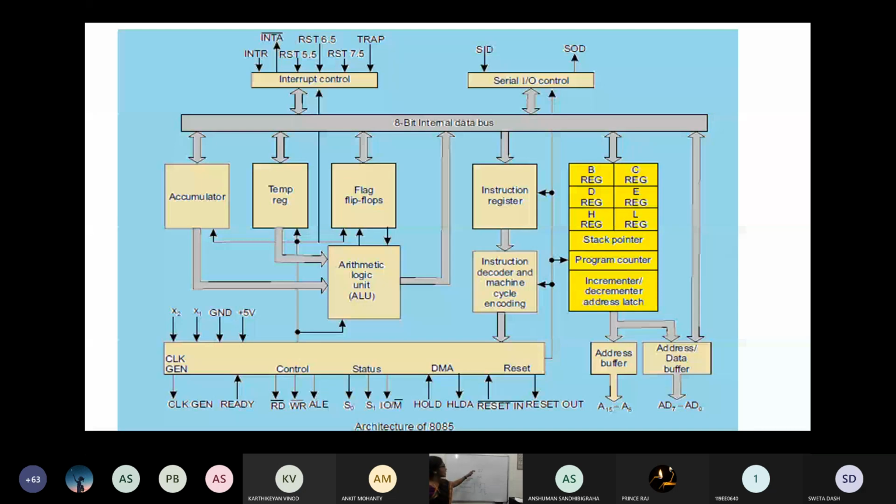This is how the control signals read and write work for a commercially successful 8085: active low. Read and write when they are low, that means it is doing the operation. When they are high, that means they have done the operation. This is how they are bifurcated. It's a technical aspect which is already with the commercial system. It's already in the kit. The kit works like that only. Shweta, you can design a kit with the other one also, read with high and write with high. Is that fine?